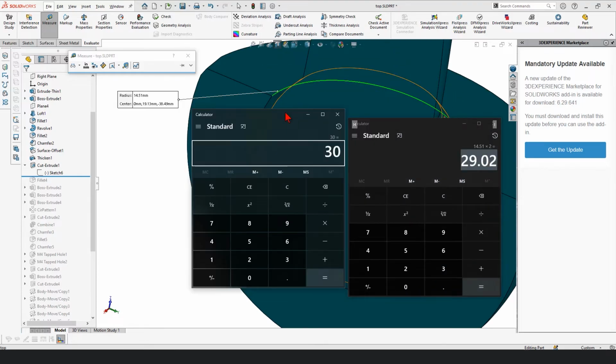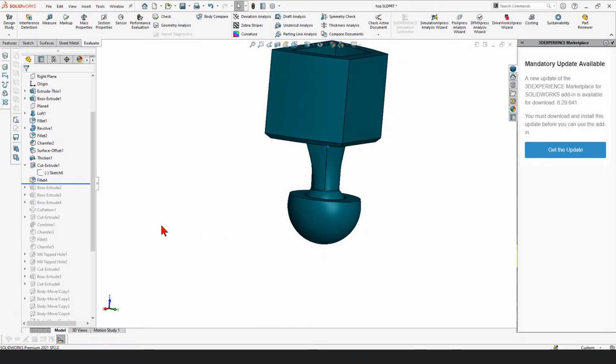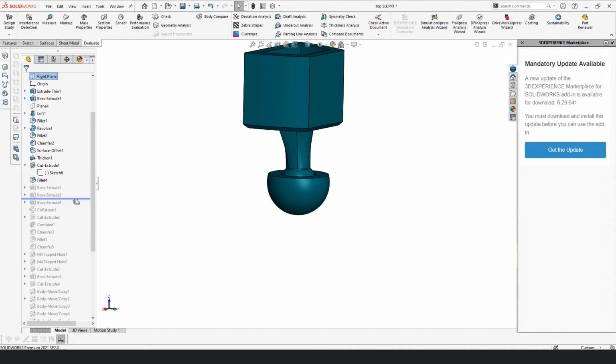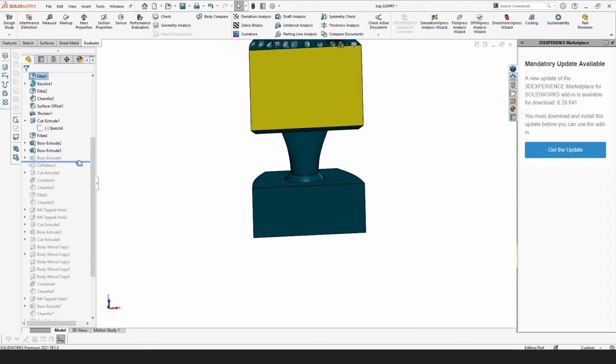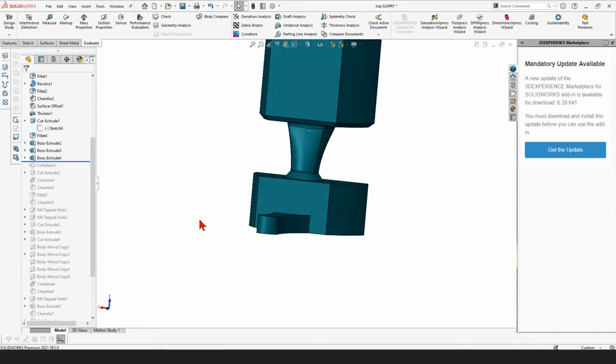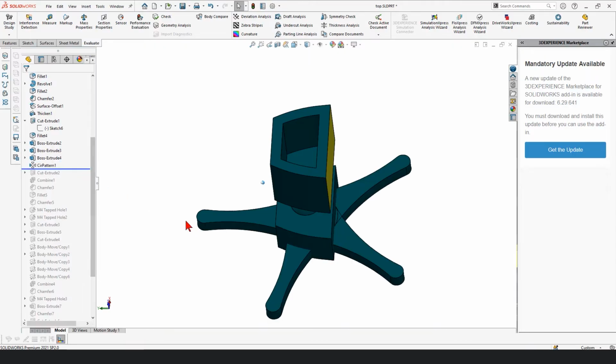Now, once I do this, I have to proceed to stage number 6, which is designing the rest of the joint, because the joint is not only carrying one function, it's carrying two functions. The first function is to accommodate the ball. The second is to have a big enough cross section so the light wouldn't tilt over. We don't want to go too big because the 3D printing will become too expensive. We don't want to be too small, then we haven't solved any problem. The light will still tilt over.